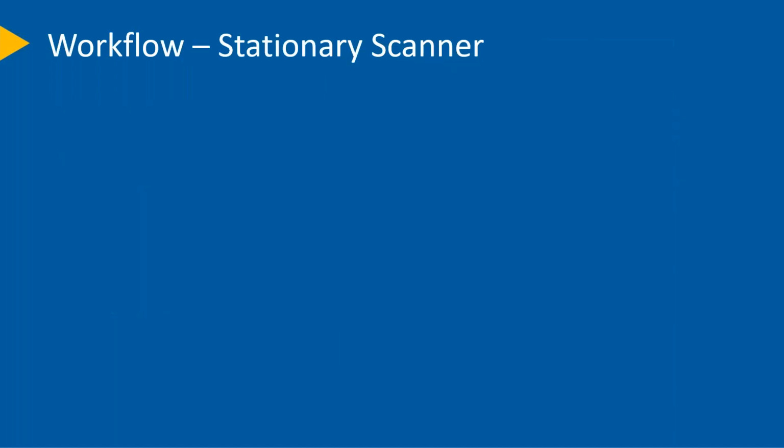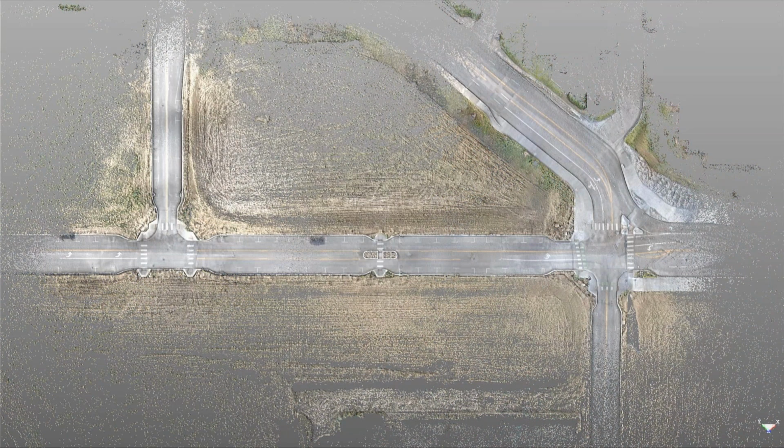Now, if we look at the workflow for a stationary laser scanner, you'll put the scanner in one position and do a 360 scan. It'll scan everything in sight, basically, except for right underneath the tripod in most cases. You'll do that, and then you'll move to the next position, and then the next position, and you'll continue on scanning all of the positions that you need to be able to see in 3D all of the data that you need to complete your project. And this all registers or comes together to connect these in one final cohesive point cloud. We'll talk a little bit more about registration and putting these scans together later.